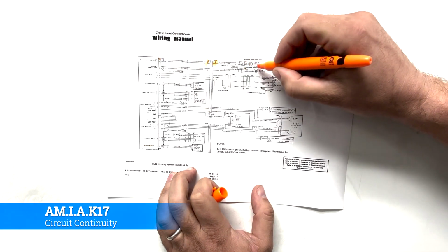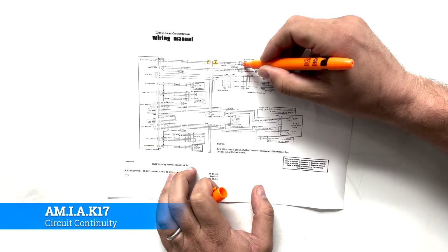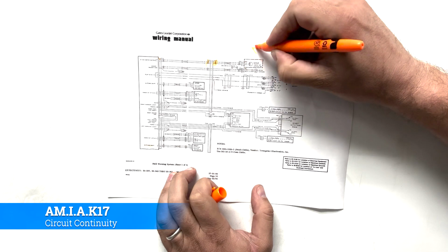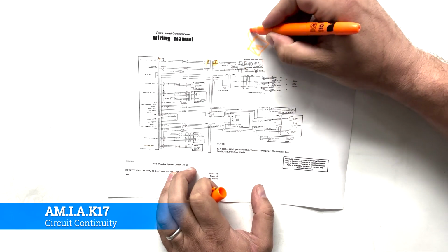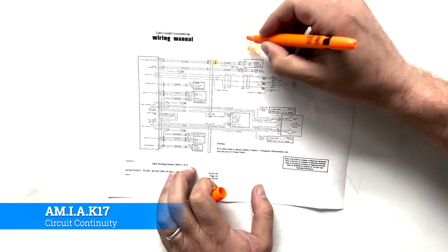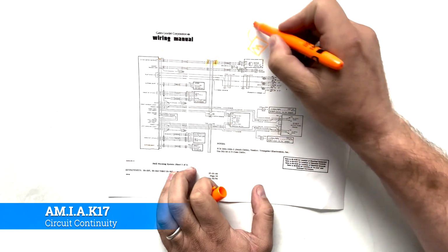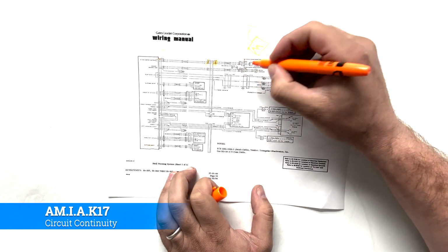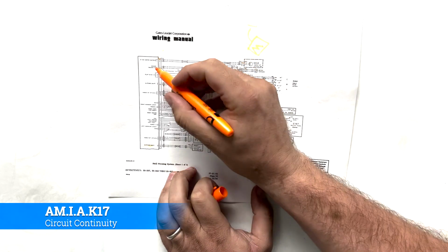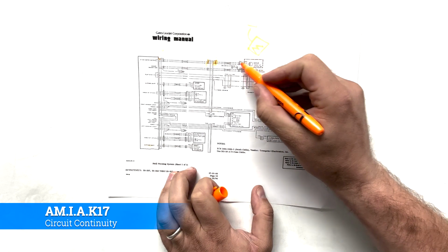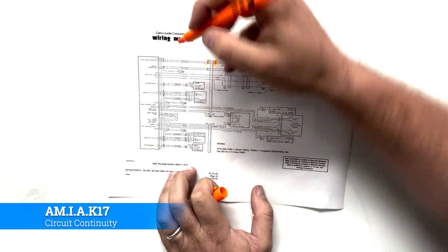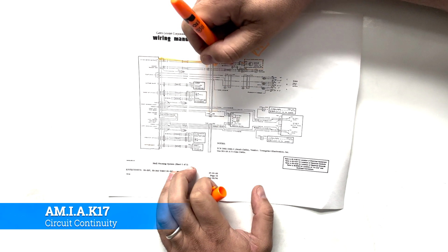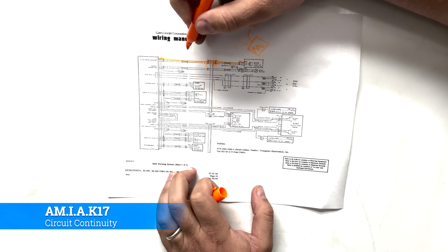We would then come back to M32, take this connector off, PE94, and we would take our meter. Remember our meter? One lead's going to go to ground. So now you have a connection between these two, right? And you're going to have another lead that comes off and pins to E. If we get a ring, if we show that we have continuity down from pin G all the way down to pin E, then we can go on to the next thing.